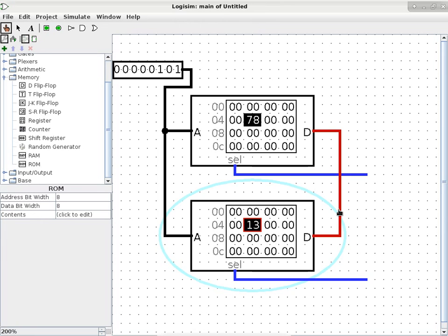In this case, you have 1.8 amps and 1.8 volts, so it's 1.8 squared. I'll just call it 2 by 2, which is 4. So you have 4 watts of power to dissipate in a tiny little transistor that's only 20-ish nanometers square, 20 by 20 nanometers. That's not a whole lot of surface area, is it?